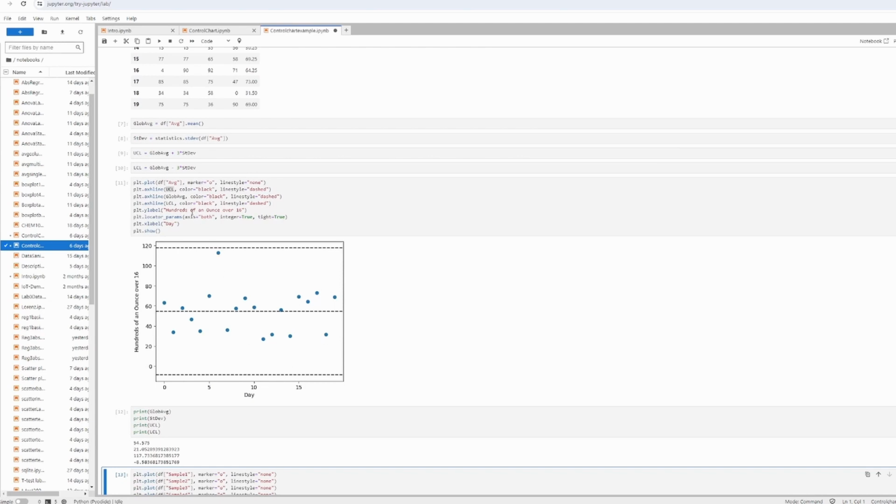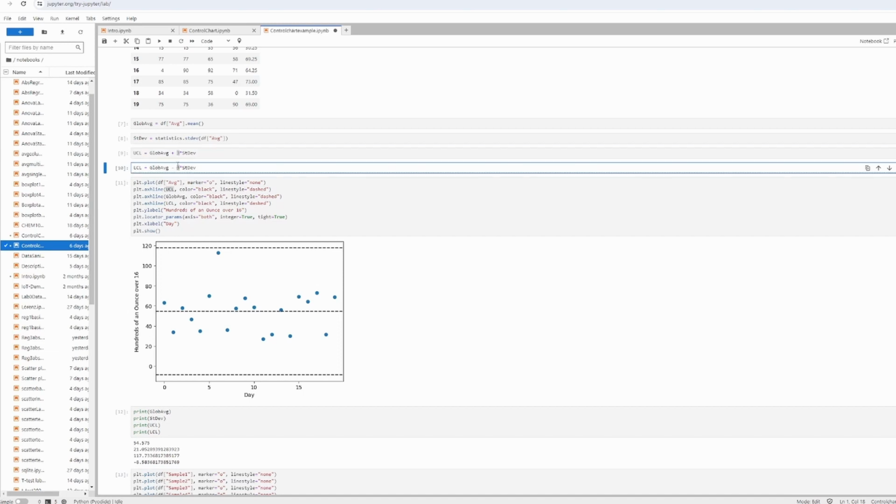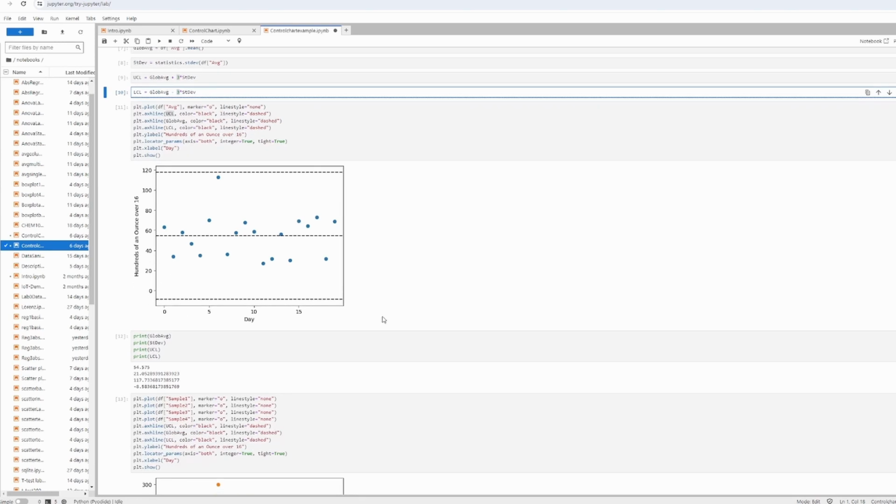And so now when we changed to 3 standard deviations, you can see that this is within control now, considering we wanted 3 standard deviations. So again, this is not arbitrary, but this is the value that you can change to change these levels of the control charts depending on what type of system you've got. And as I said, in industry, typically 3 standard deviations is the starting point for starting to monitor your process.